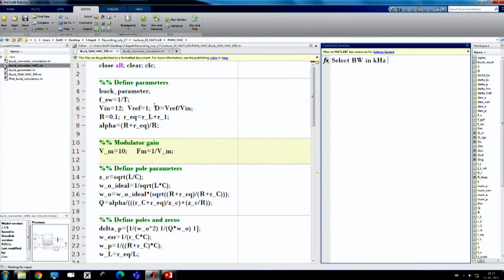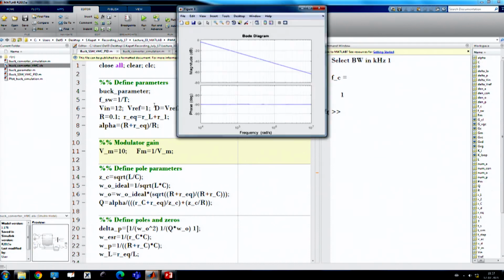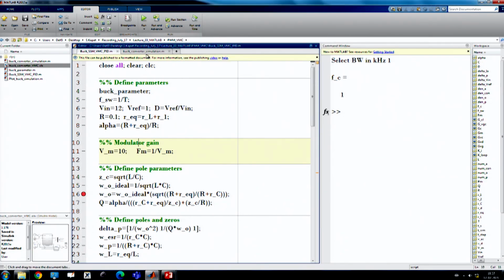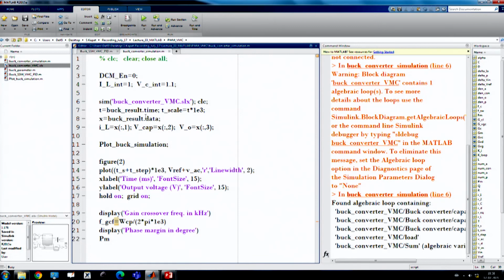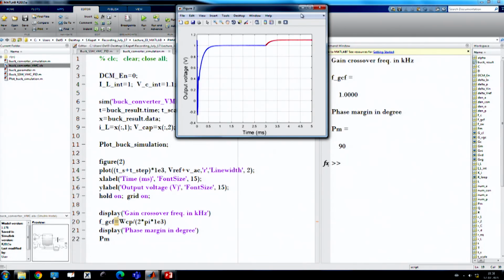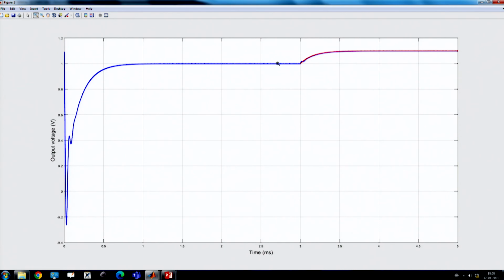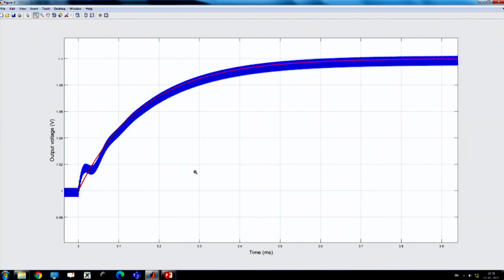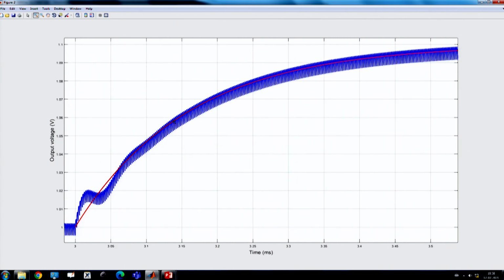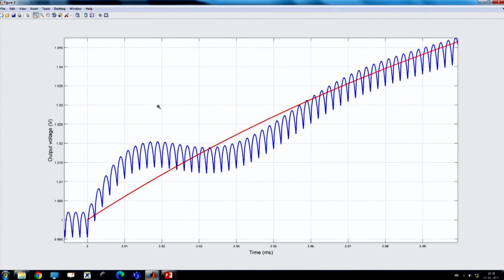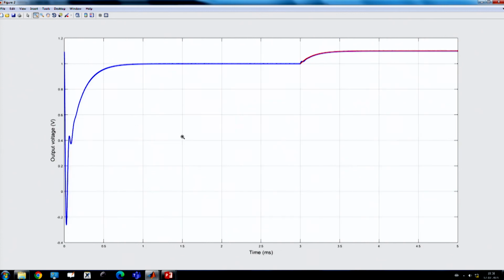If you further reduce to, let us say, 1 kilohertz, which is very low, then I want to match the switch simulation. It is 1 kilohertz, 1 by 500 times slower. It is very slow, and if you see the response here, they are matching quite nicely except for the initial stage. That means the converter is behaving like a first order except for the very initial stage, where there is a slight deviation. Although we are trying to achieve first order, with actual voltage mode control it is very hard to get a first order response, at least for this simulation.